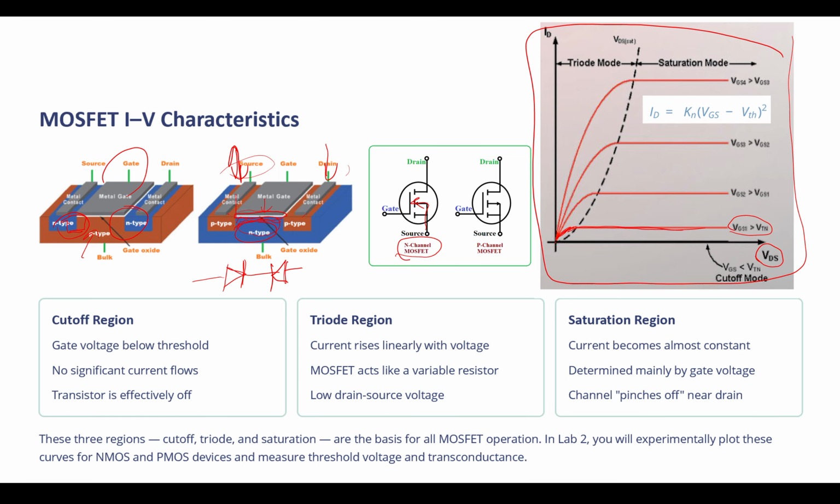So if we have 0 voltage between the gate and source, we are in a cutoff region. No current would be transferred between drain and source. Now, if we apply a voltage between the gate and source, we are starting to polarize the channel, making it a conductor. Now we are allowing the current to pass.